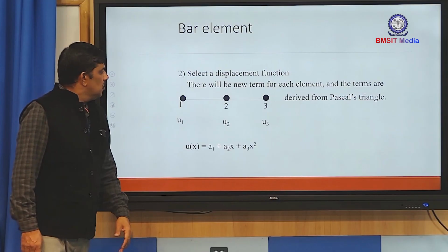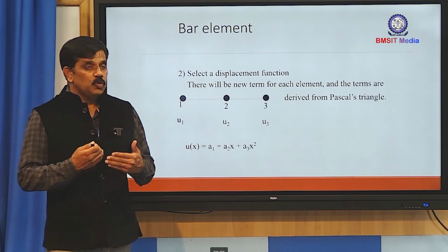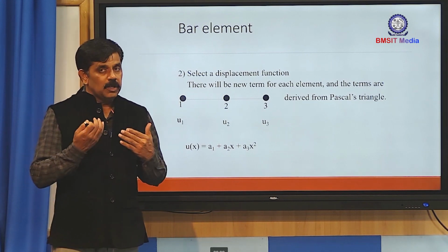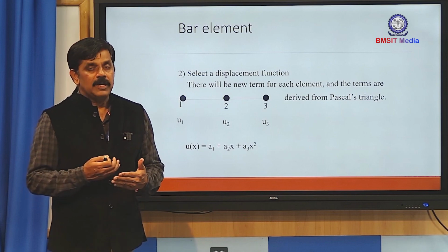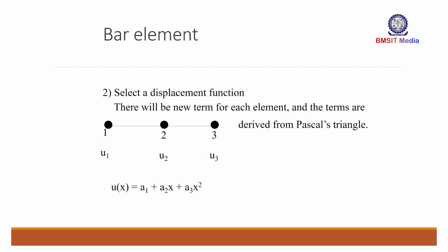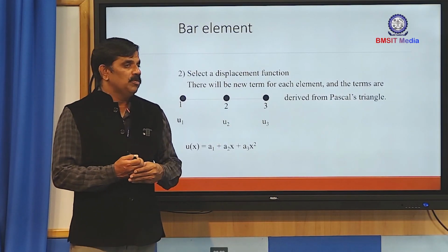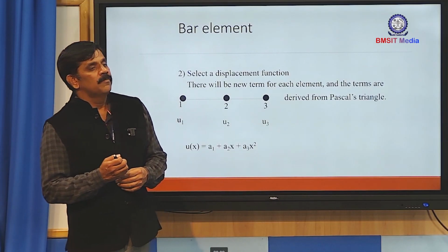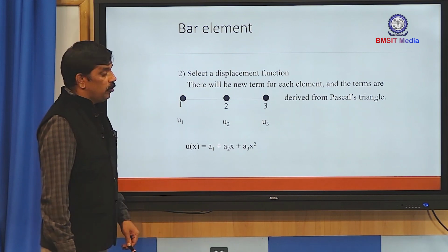We have discussed how to solve an engineering problem by the practical approach, the numerical approach or the analytical approach. When you come to the numerical approach, or finite element analysis, you have to find the displacement, so you have to define the displacement. We can define the displacement using two types of equation: polynomial equations and trigonometric equations. In most cases we use polynomial equations.